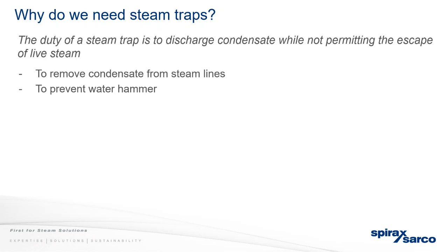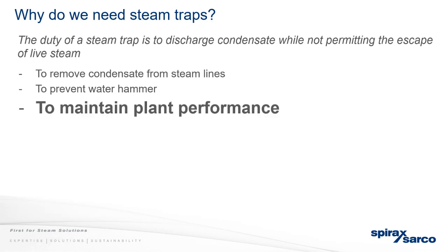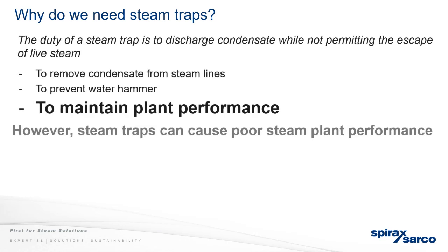So it also prevents water hammer to maintain plant performance. The drier your steam, the more enthalpy it has to give up, and the less damage it does to equipment. So they're integral to your steam system.